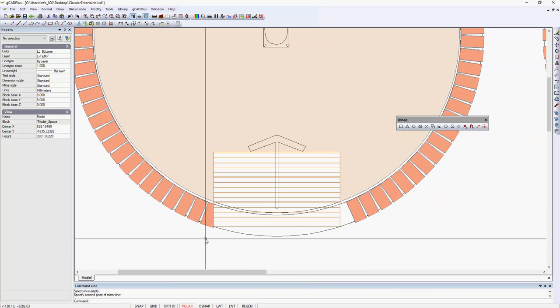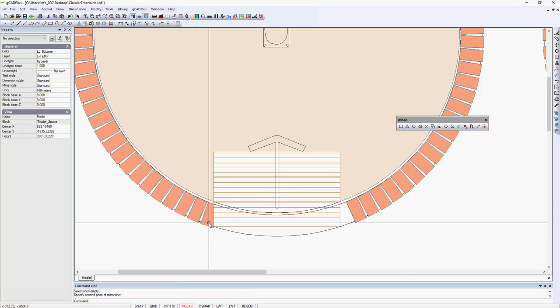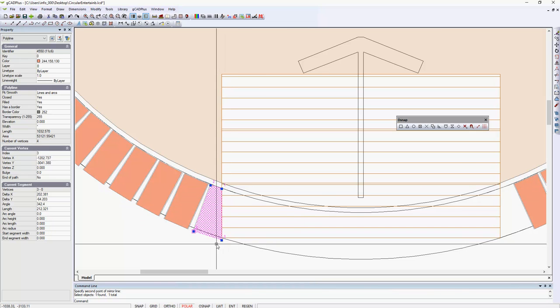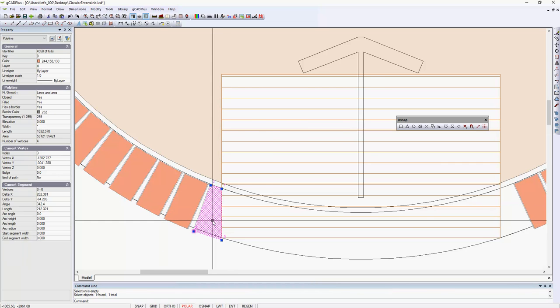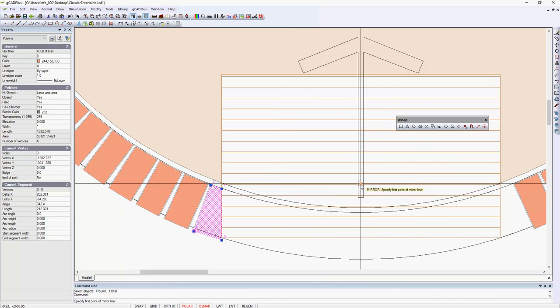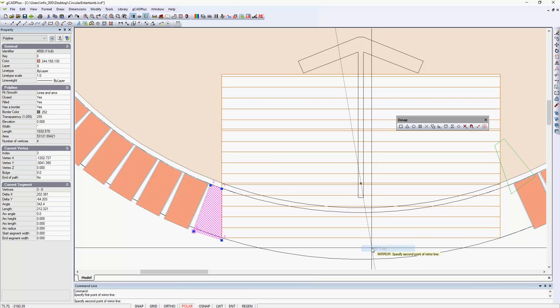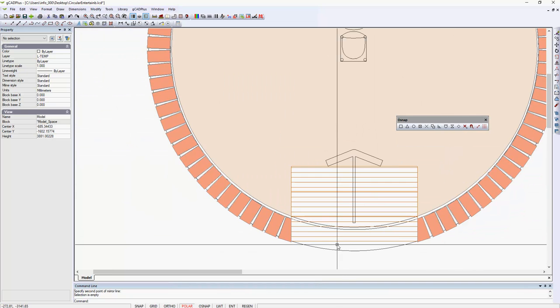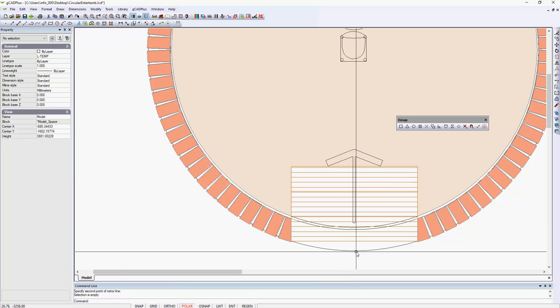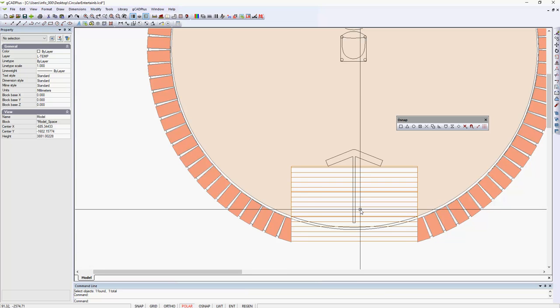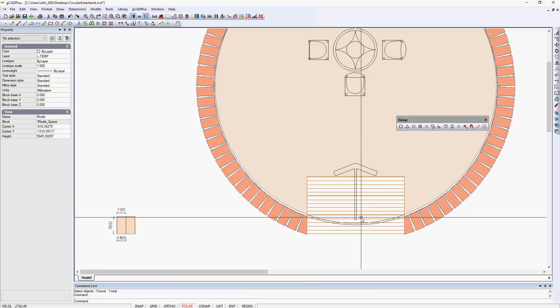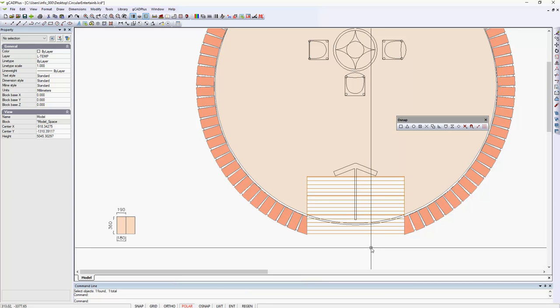Well, if you wanted to be really fussy, you could take that last paving brick, that overlapping line which needs to be cut. You could select the polyline there and move the vertices of the polyline into an appropriate place. And then you could select it and mirror. We need to find a midpoint somewhere here and down there, and right click with a copy, and there's our cut paver or slab on either side of what will be the entrance. We could then remove that outer circle, and there's the entrance to what will become quite a useful block if we're going to have a circular sort of entertaining spot in a garden. Would make this into a block.